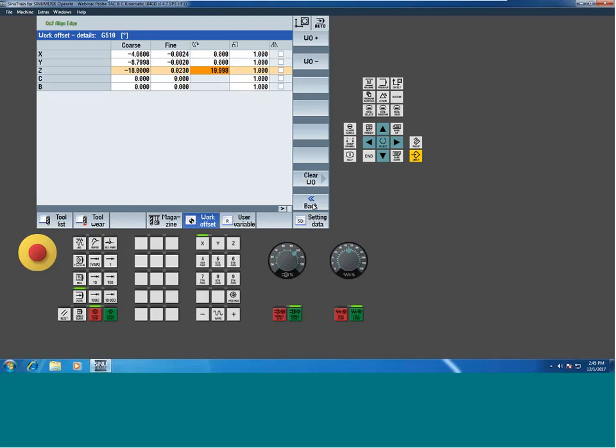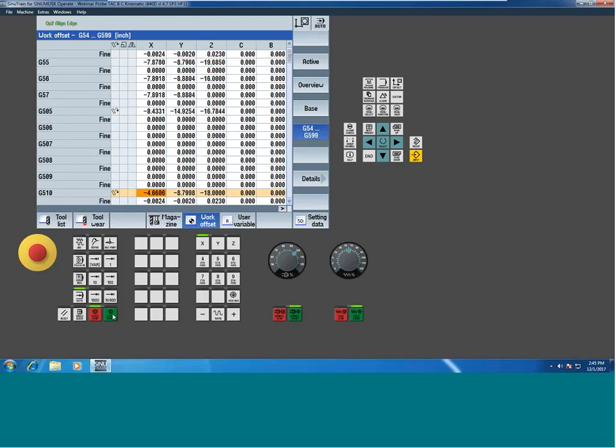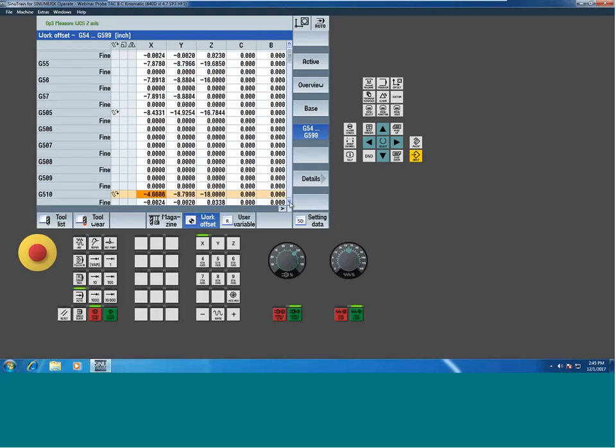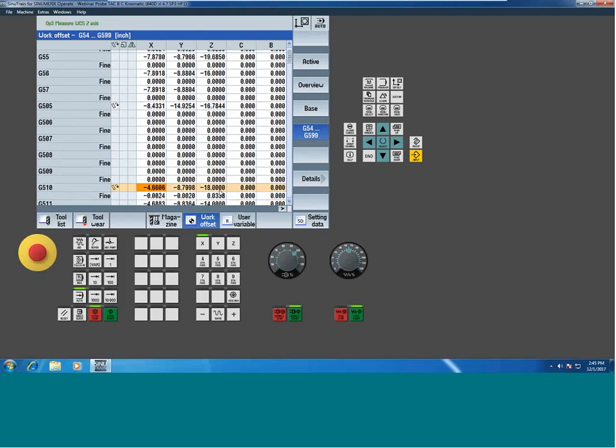Okay, so we're here. Now we're going to cycle start. Machine is going to come around, and it's going to measure my Z-axis. So now if I look at my fine value, I now have a 338 as opposed to originally I had 230. So now if I looked at the cycle, I'm just adjusting the fine of G510, so it's only going to update that one field. And when I do one more measurement, it's moving around the X and Y, and then it updates my fine fields. So now I've aligned and reset all my XYZ locations, so I truly know where that part is.